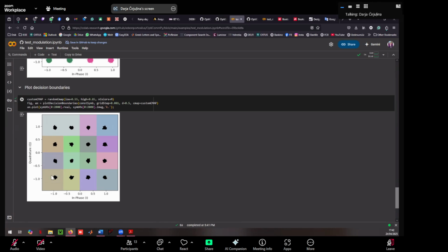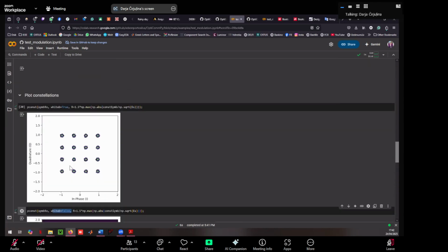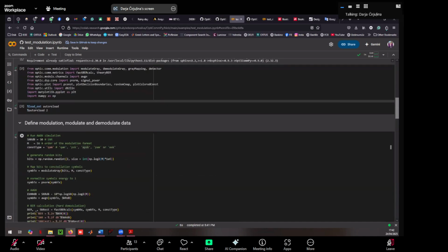If we decide to lower the SNR value, for example, to 10 or 30, you would see that the symbols would be more scattered. And in these cases, we really need to draw the borders and make a decision: does this point belong to this symbol or the next one? So you can try this code with different modulation formats, different SNR values, and please add your graphs, your findings, and of course your analysis to the report.